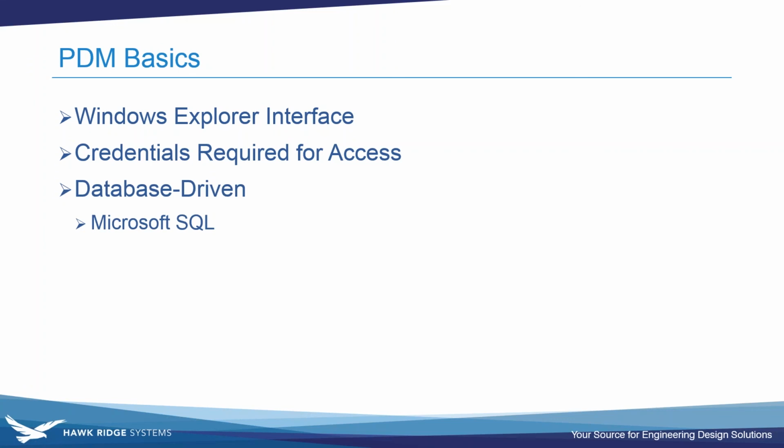So all the information about our file, including the file references and any of that data card information, is also going to be stored and managed by SQL. So if you rename files or move files, it's not going to break the reference anymore. And that's also allowing us to store additional information, project information, material properties, things like that, that wouldn't generally show up in the Windows Explorer interface.